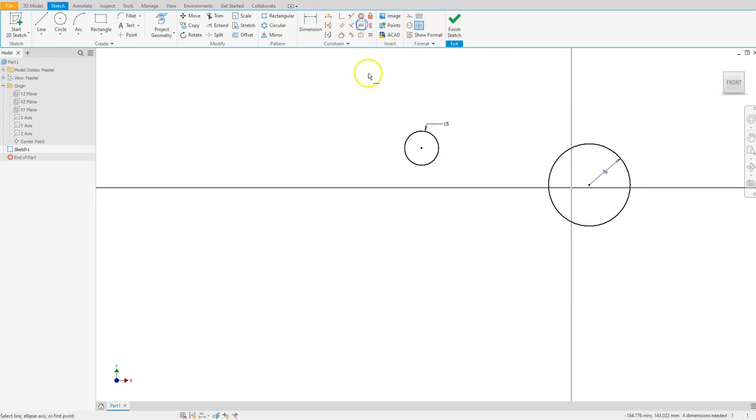So let's choose horizontal. Let's choose this center. And you can see right when I highlight the center, you should get a dotted line that's showing you which direction. In some cases, depending on how your drawing is orientated, you will pick one that says horizontal and you don't know if it's horizontal. But in this case, I'll go ahead and select the vertical just to show you what I mean. You can see when I hover over that dot, I'm getting a vertical dotted line. So that's going to tell you which way you're going to orient these, horizontally or vertically. So let's go back to the horizontal.